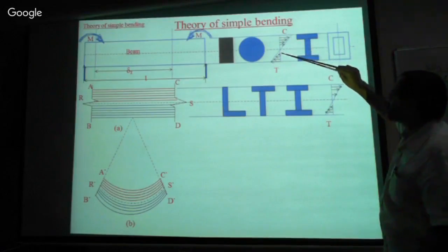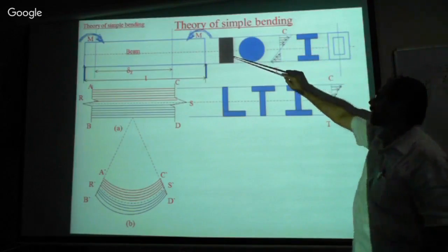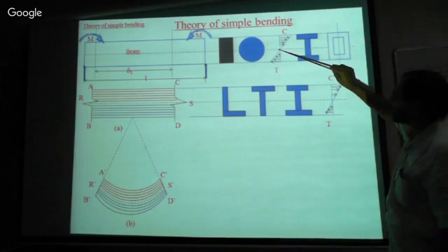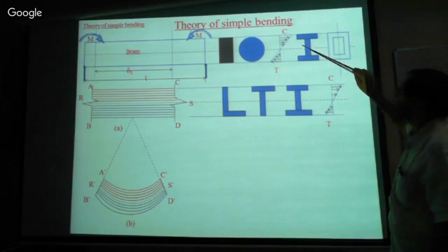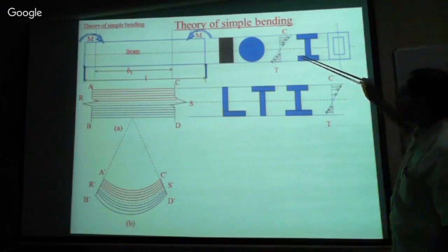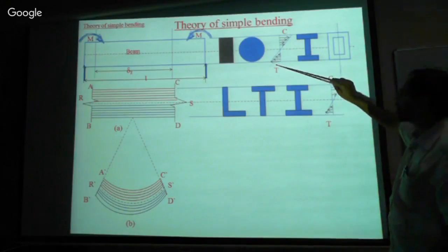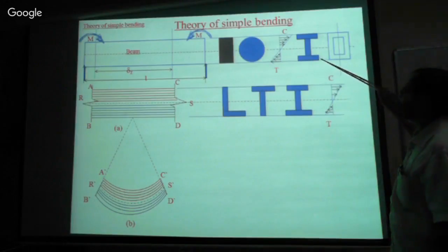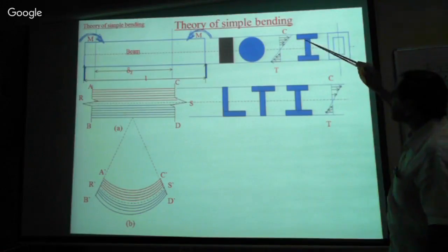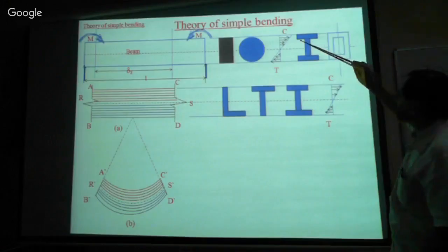That is why, instead of making a rectangular beam, because zero stress is available at this point, the material is less in this portion. The maximum stress at the compression requires the maximum section, according to the compression. At the bottom, again, according to the tensile stress available, the section is made. In this region, minimum section is required. Therefore, we are saving the material of this portion.